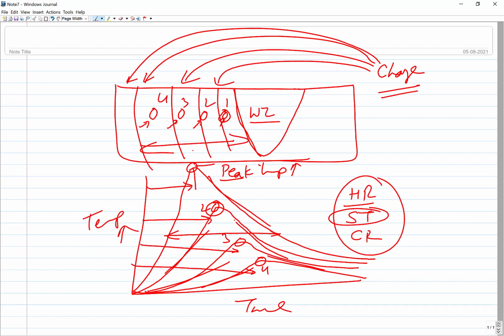Okay, so again, if you increase the heat input, your peak temperatures will change, cooling rates will change, heating rate, everything will get changed. So this may be for one heat input, say 1 kilojoule. If you go for 2 kilojoule, you may get different weld thermal cycles.